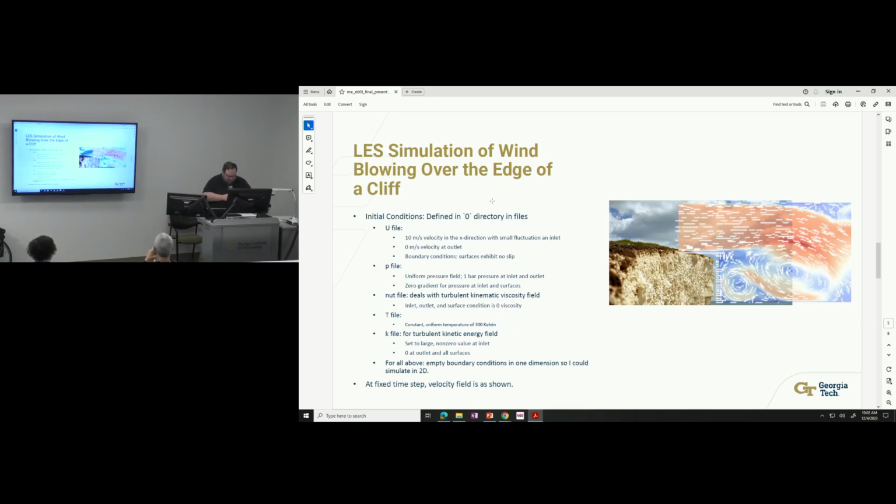So small scales of turbulence result in higher frequency turbulence, and that affects the fine details of the beam. It's more significant near the transmitter or receiver, not really significant along the propagation path. Large scales result in low frequency turbulence that causes large distortions in the beam. And that's why I chose a large eddy simulation that I simulated through OpenFOAM, which is a CFD software.